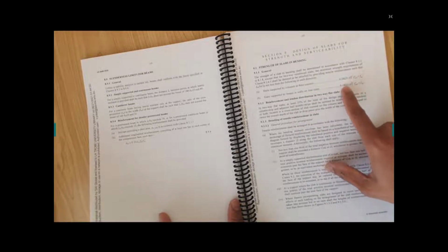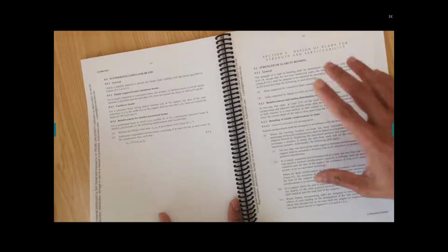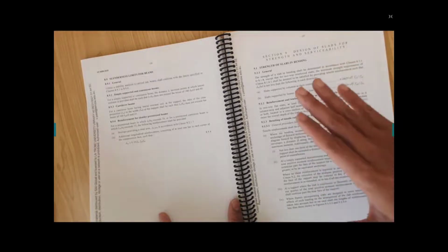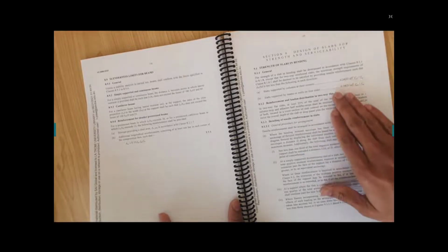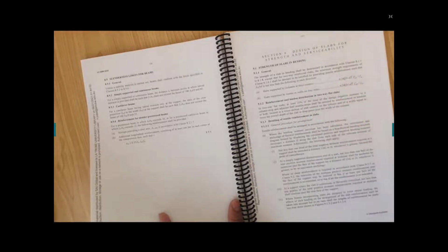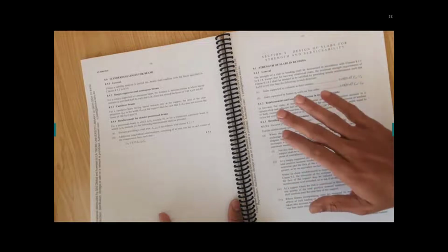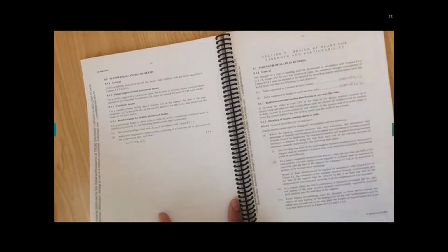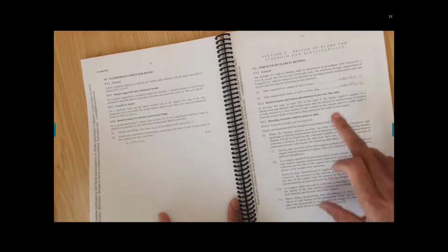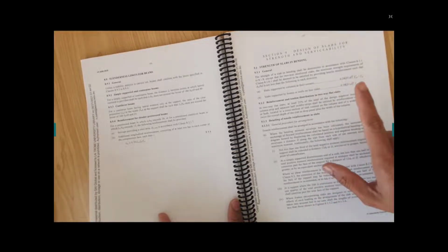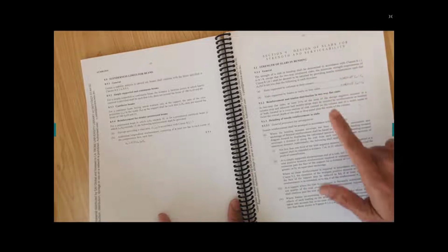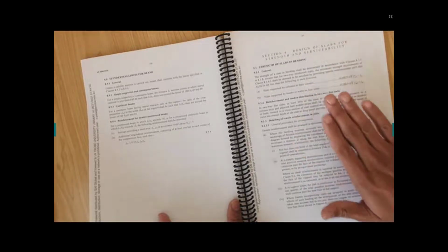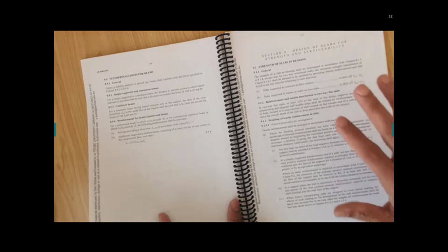Now this Ast minimum is to prevent the structure from brittle failure. Your structures will not come down. So regardless of your design, regardless of your moment, regardless of your cover, regardless of your span, whatever you do, plus minus multiplication division, you make sure that the Ast you have calculated is more than this one. No questions to be asked, and I don't want to compromise on this one. You must have this minimum rho in your design.